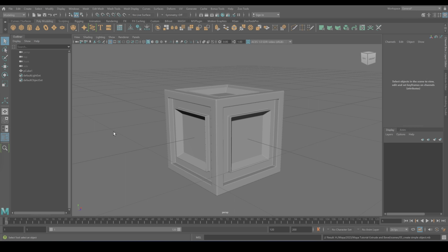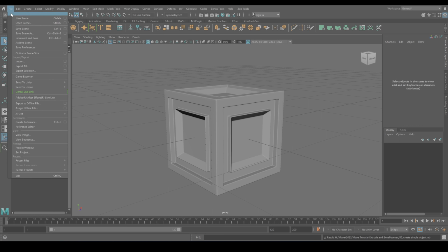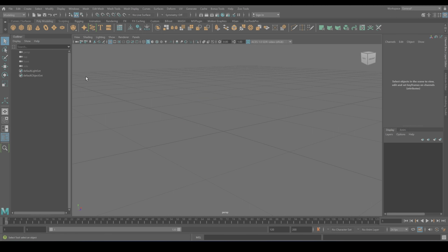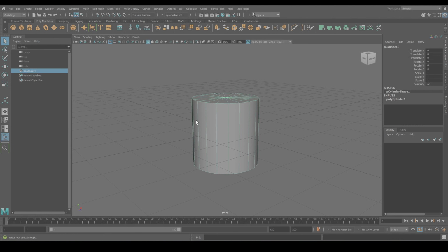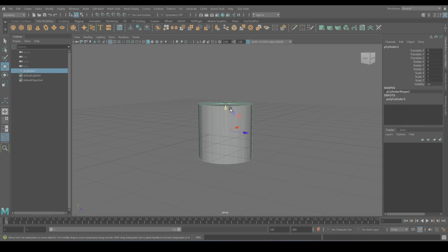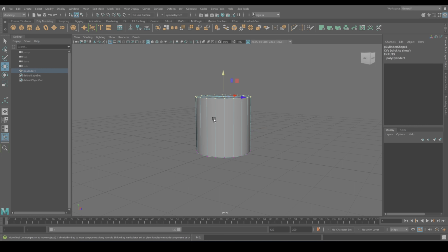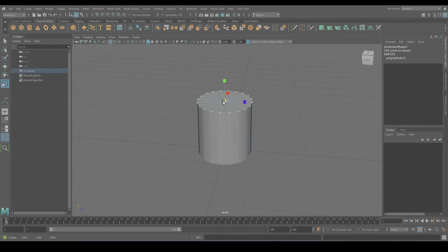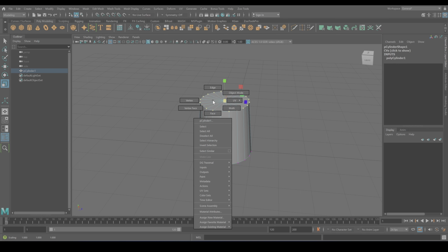So we have covered quite a bit so far, haven't we? So to put those skills into practice, let's tackle a project together. So how about a lighthouse? So that's a perfect way to use both extrusion and beveling. So please follow me. Let's start with just a cylinder. Just moving it upwards a bit, selecting the top vertices, scaling it a bit uniformly,